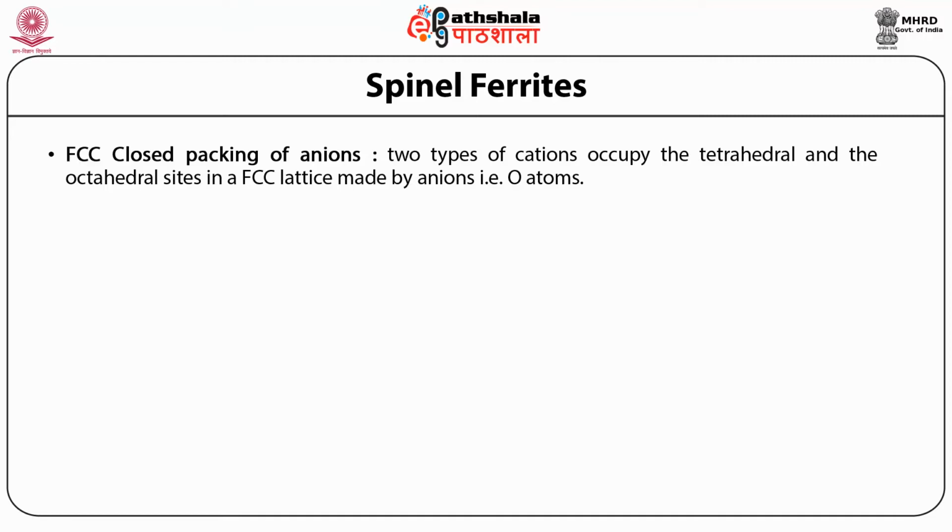One unit cell of spinel structured compounds consists of 8 formula units of AB2O4, which are determined by the distribution of cations in the interstices whose occupancy is only partial. Hence, one unit cell has a total of 32 octahedral interstices and 64 tetrahedral interstices.